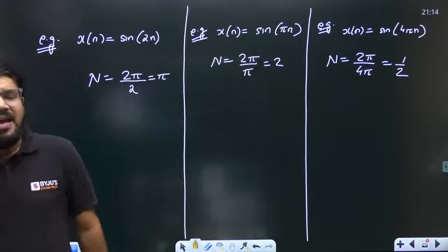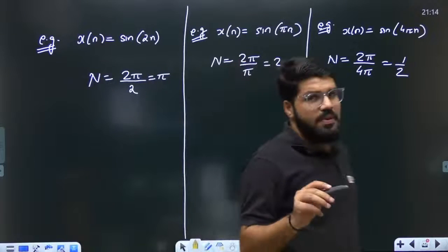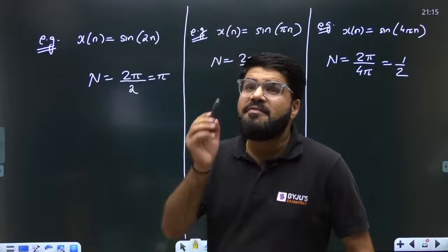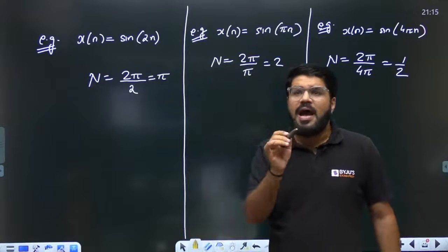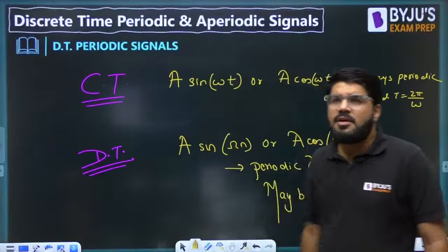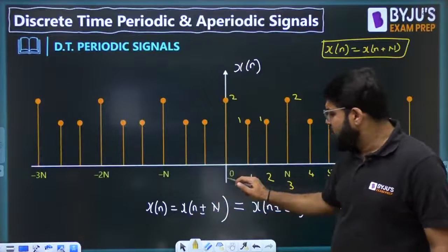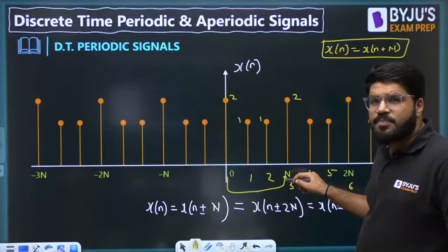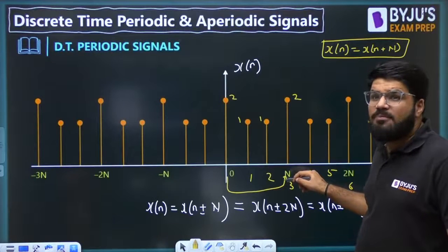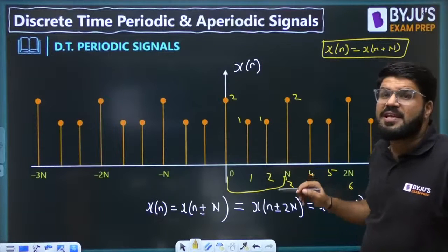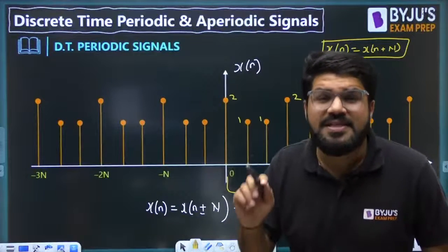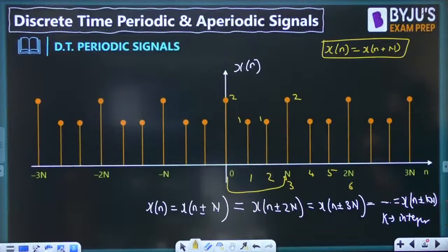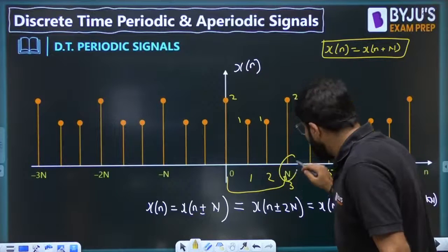The point is, here you are finding the period of a discrete time periodic signal. And the period is the minimum duration of time after which repetition occurs. If there is a value of the signal at the origin, the same value repeats at N. That is the time period N, I can say. But since you are in the discrete time domain, the important thing about discrete time signals is that they are only defined for integral values of time.